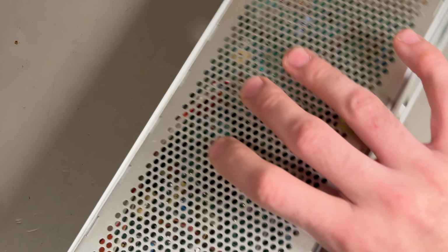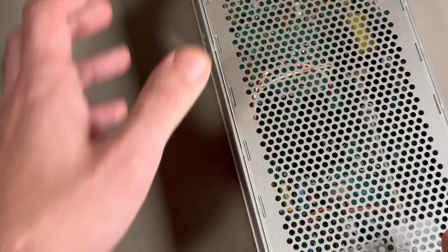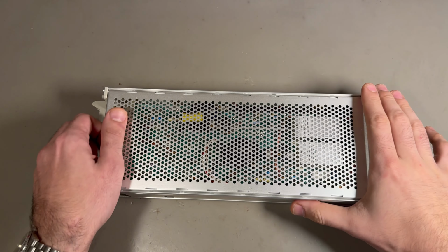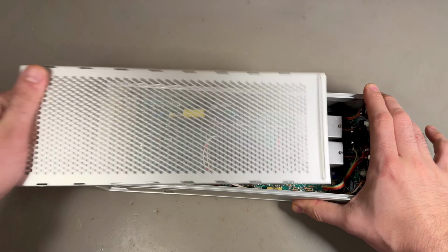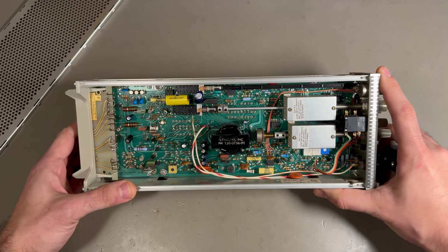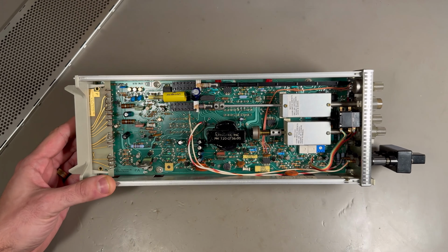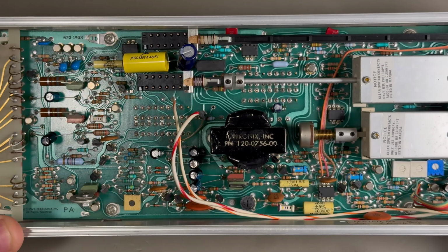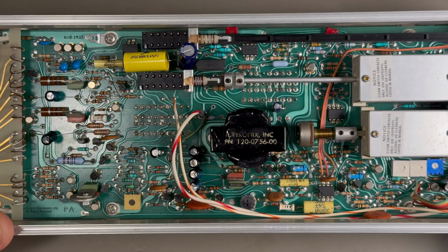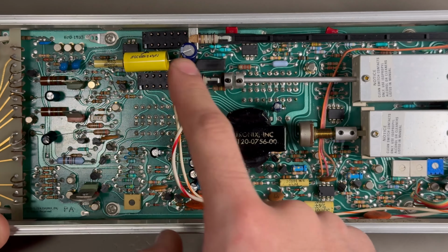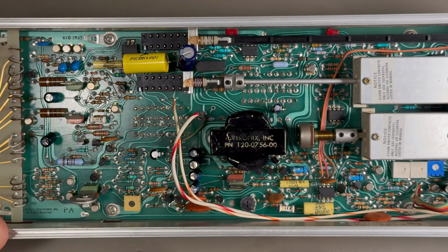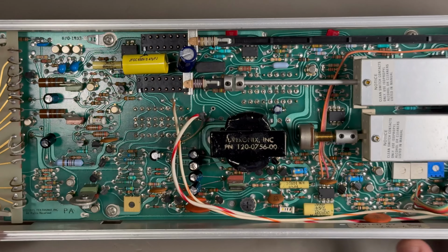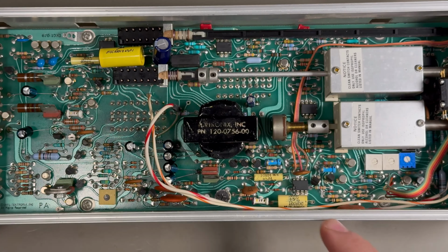What I really love about these Tek plugins is that they're very easy to take apart. You just, and you're in. So this is the entire device. Again, it's very, very nice. You can see that I've been here before and I've recapped the circuit. There's a few capacitors that I replaced. This one as well. This one's the 0.1 microfarad in the oscillator. You've seen it on the schematic. And I've changed some other parts around here.